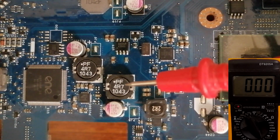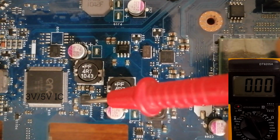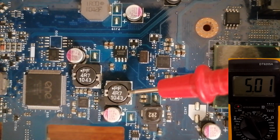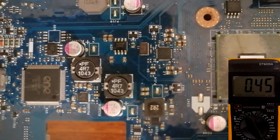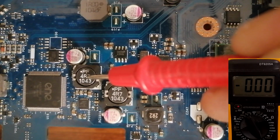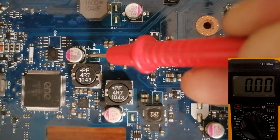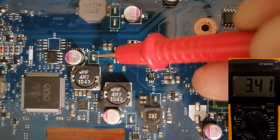For every channel we have inductor, capacitor, inductor, capacitor, and of course we have the IC, the 3 volt 5 volt IC. You can measure 5 volt in the inductor or capacitor or test point. The same for the 3.3 volt channel. You can measure 3 volt here in the inductor or in the positive terminal of the capacitor, or of course here we have the test point.